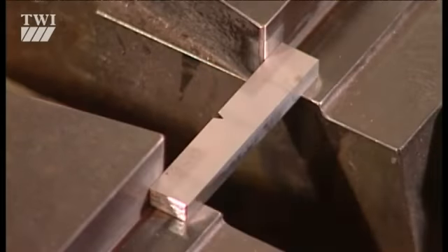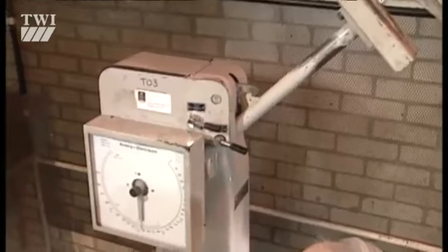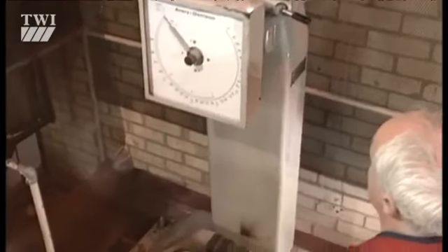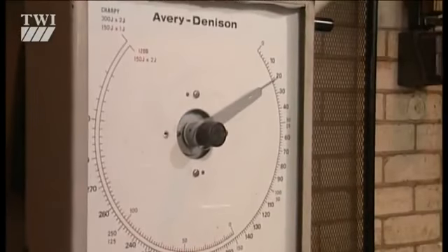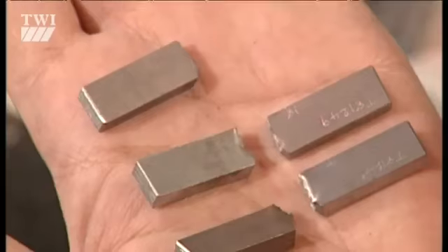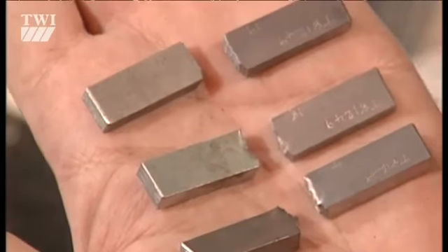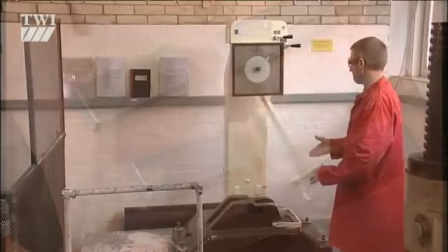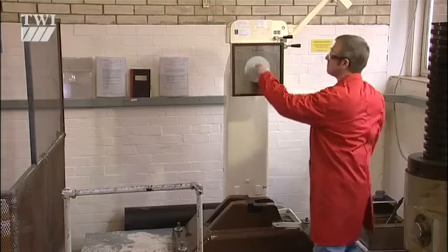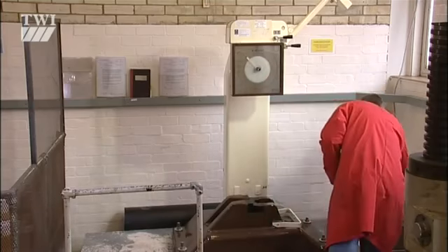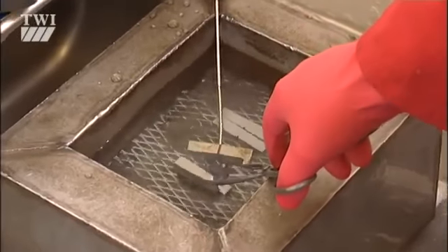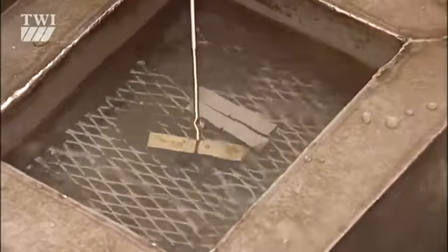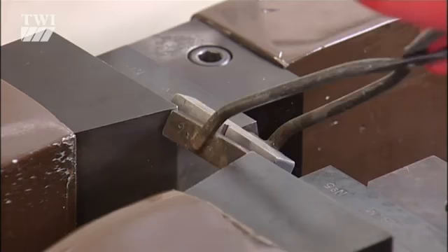Now, measuring the toughness of a material demands different equipment altogether. Toughness is broadly a measure of the amount of energy required to cause an item to fracture and fail. To measure this, we most commonly use the Charpy V-notch test. It involves striking a standard notched specimen with a controlled weight pendulum, travelling at a set speed.